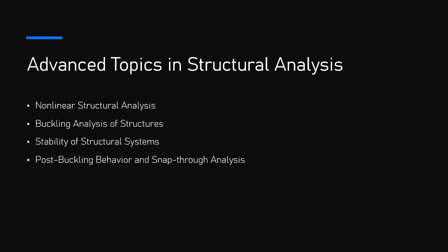10.3. Analyzing post-buckling and snap-through. 1. Nonlinear analysis. Post-buckling and snap-through analysis require the use of nonlinear analysis techniques because the structure's deformation is large and cannot be captured by simple linear models. Finite element analysis, FEA, is commonly used to simulate and analyze these behaviors.